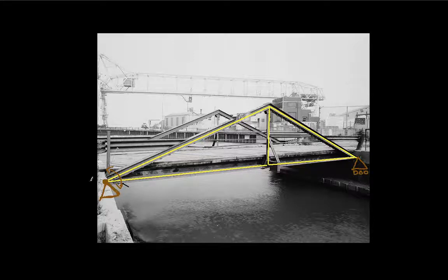The reason for doing it this way is we'll have a reaction force in the X and Y direction here. We'll have a reaction force just in the Y direction here. And it turns out without that sort of assumption that one side is on rollers, if we had another reaction force here, then it would actually not be possible to determine what these two reaction forces are.